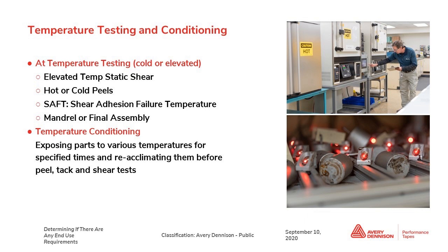Another great test related to how we determine the service temperature is the SAFT test. SAFT is an acronym for shear adhesion failure temperature. It's very much like the static shear test, except in this situation we ramp up the temperature. We have conditioning ovens that can increase the temperature at a linear rate. Generally for that test, we start at 100 degrees Fahrenheit and go up at a certain rate until 400 degrees Fahrenheit. Something like an HPA would not fail in that situation, but a general purpose rubber would fail relatively quickly at, say, 160 F.